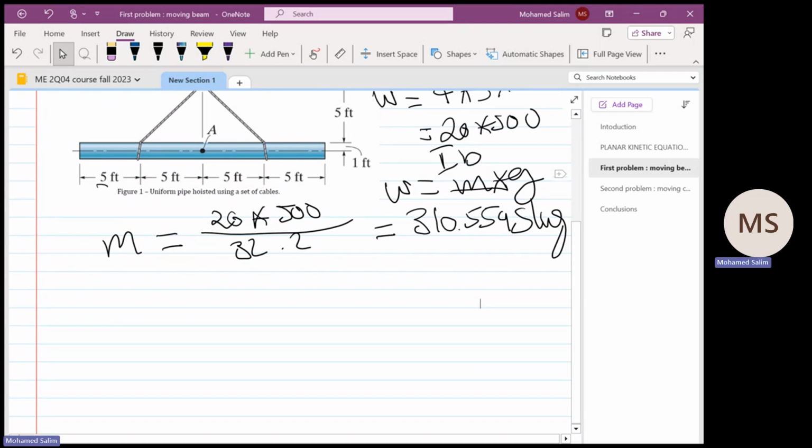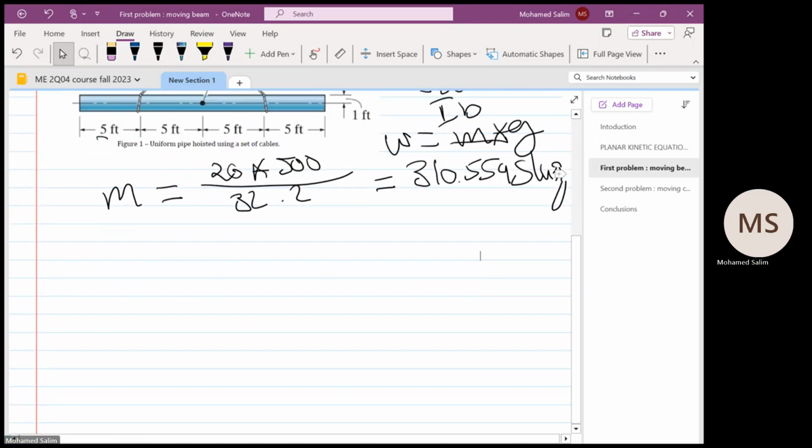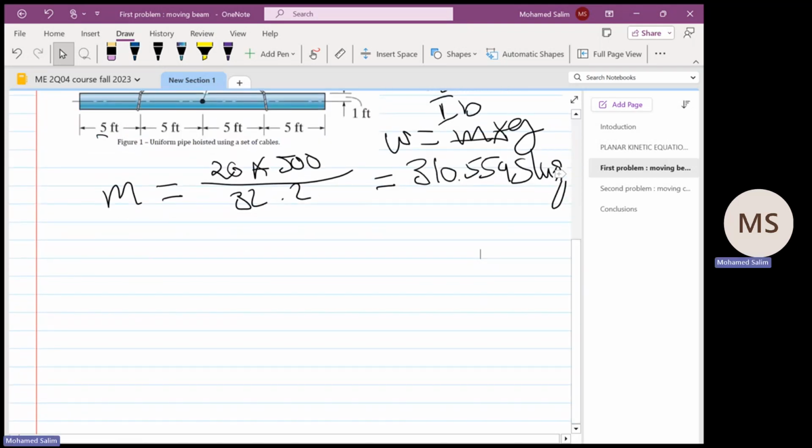Moment around A, external moment or internal moment? Say external. Internal. Why? Point A is inside the beam, and there is no application of any external moment. Good. So we need to what? To divide the beam at point A.